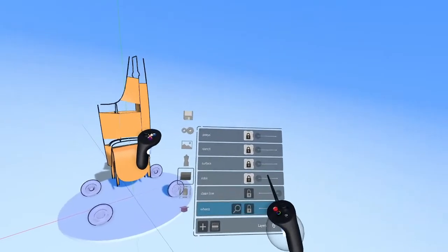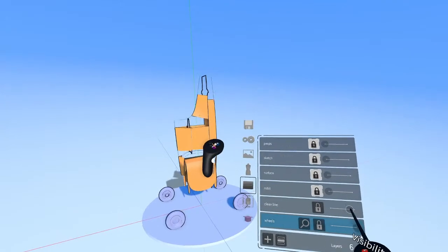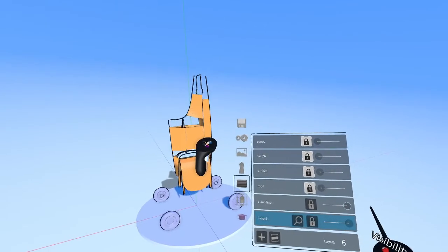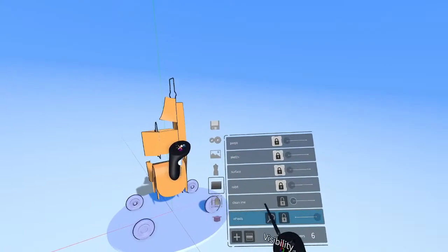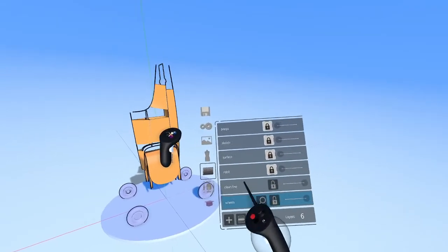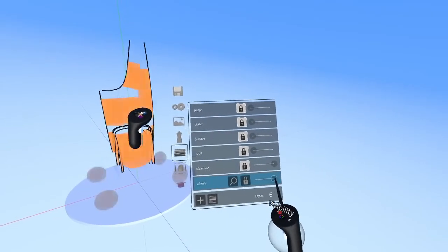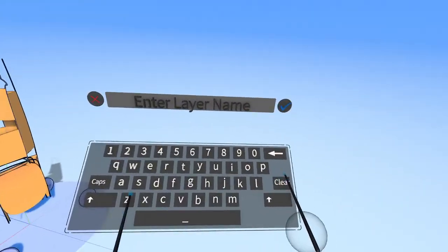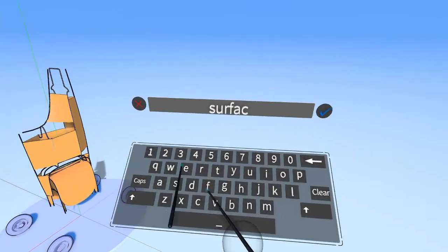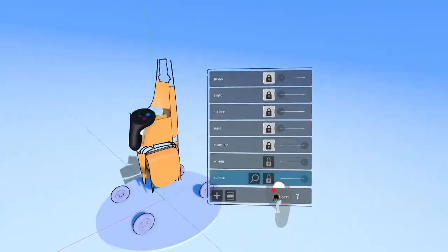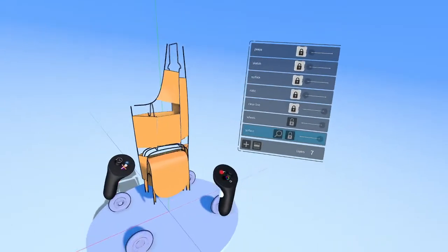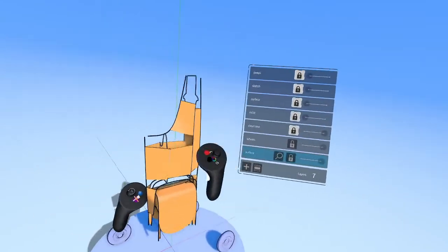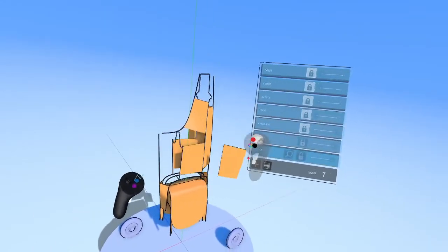What I'm going to do is turn down everything else. I'm going to turn down our robot sketch, and we'll leave the curves here, but we're going to lock them. Okay, and so this is my mistake. All of the surface geometry is on the wheels layer. So we're just going to create a new surface layer here and grab these surfaces and drop them on that surface layer.